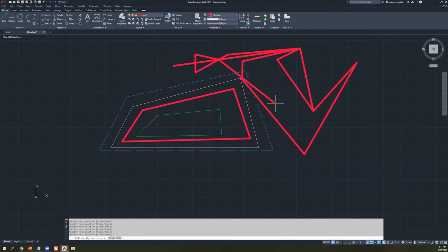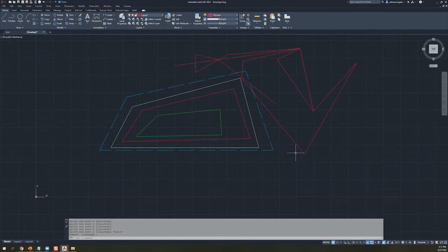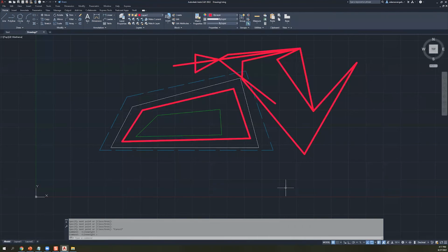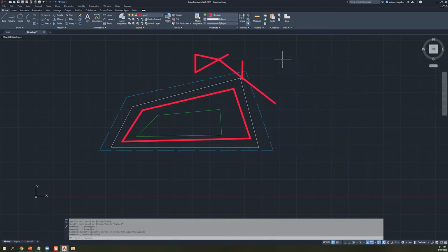It's not always clear when these intersect or when they don't intersect, and maybe you have to make your snaps particularly smart or anything like that. It can be kind of a hassle, especially when you're not working precisely. But that's the reason why people may want to toggle this on or off, right? I could work with it off, make sure I'm placing everything where I need to place it, and then boom, okay, this will look good on a print. Why not? That's when people start using that line weight function over there. So something to keep in mind for sure.